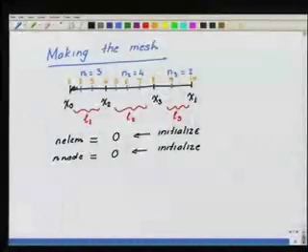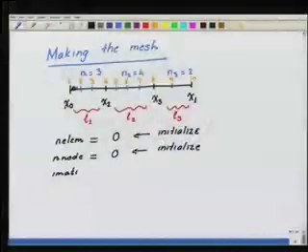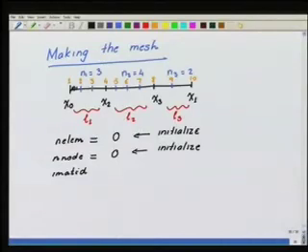Now, the way we have written the program, we have to know what material properties to use in a particular element. If I am interested in this element, how does the computer know what E to put there, what A to put there? Somehow I have to inherit that information for each of the elements from somewhere. So we are going to have an ID or a pointer or an indicator of which material domain a particular element lies in, through this vector imat id.